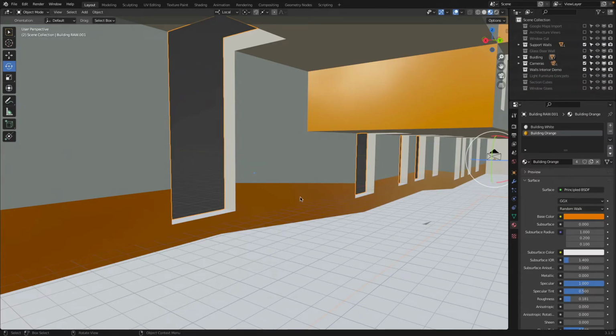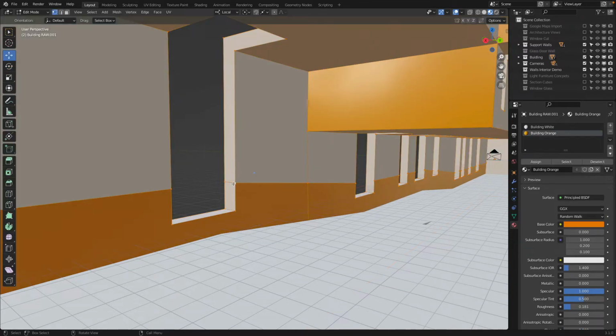The last piece that's maybe good to know about the knife is, if I would like to add more to it, let's say instead of being at an angle, I would like this to be horizontal. In edit mode, I can press K, snap to this point, press X for the x-axis, click and enter, and then I can select this face and give it that material.